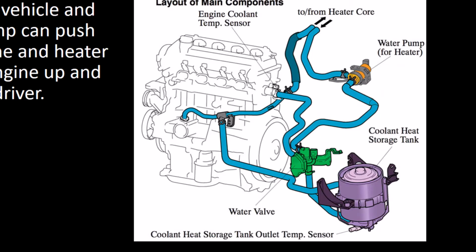As you can see from my picture here, we have our coolant heat storage tank. So this is that insulated tank that has pumps and valves so we can move fluid into it. This is where it's going to get pumped. So when you turn the key off on a hybrid vehicle like a Prius, it's going to pump hot coolant into the storage tank, hold it there, keep it hot for at least a solid 48 hours. And then when you hop back in, it's going to dump that coolant back in, make everything warm again.